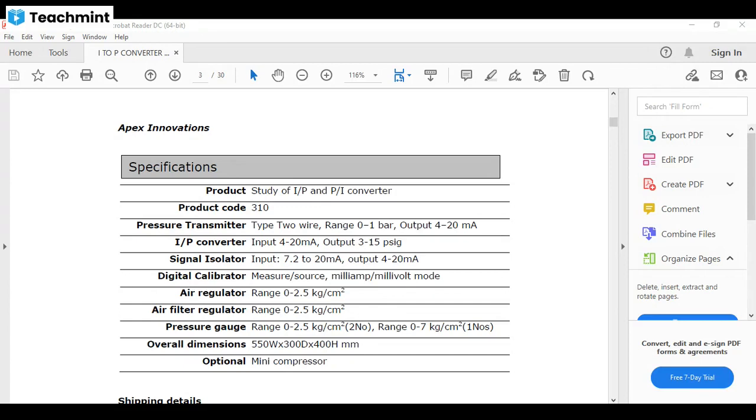If the current is more, then the power of the magnet will also be more, the flapper moves closer to the nozzle, so less pressure escapes through the nozzle, and the output pressure increases. If the hole is smaller, the pressure will automatically increase, because if we pass more pressure through a smaller hole, the pressure at that point will be higher. In this way, the output is proportional to the input current.